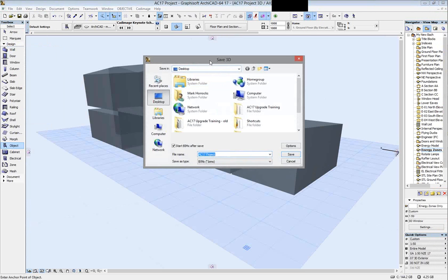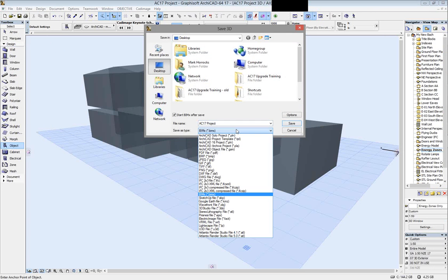Well, Save As. Mark may not have this installed, but what happens is at the bottom you'll have a gbXML format, and you can just save that file. It's appropriate if you ever go into some structural or thermal analysis for engineers. They generally require a gbXML file. It is quite a popular format for their software, and this is just a way to communicate with them.